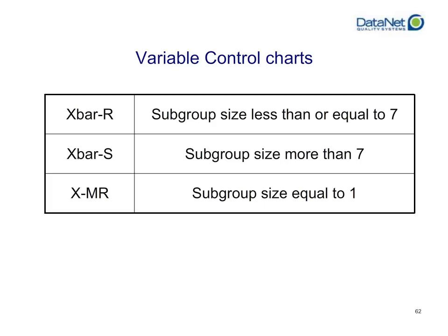An X and MR chart is the X and moving range chart. This is only used when your subgroup size equals 1. When your subgroup size equals 1, you plot every single individual reading onto the control chart as a subgroup. But because you can't do any comparative analysis on a single point of data, you can't do an average on a single point of data, you can't do any sort of capability analysis on a single point of data, there's no difference between a single point of data.